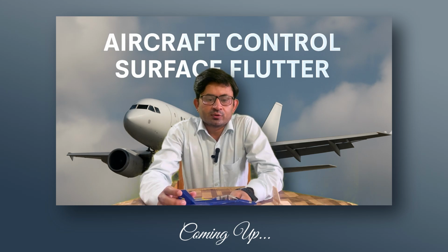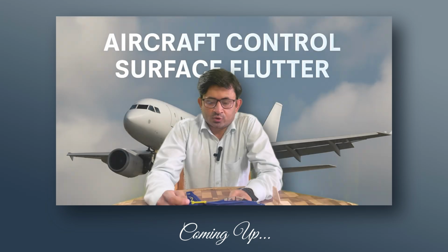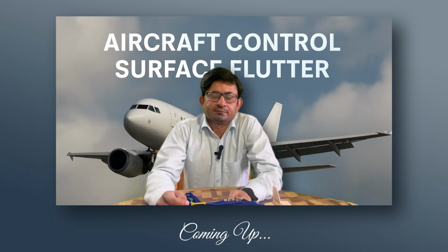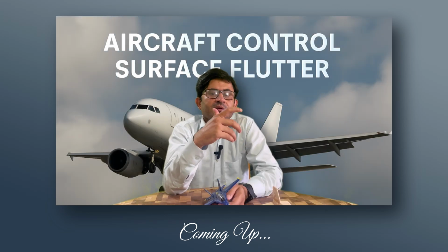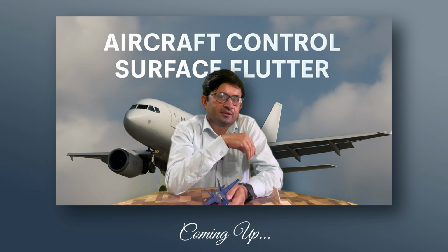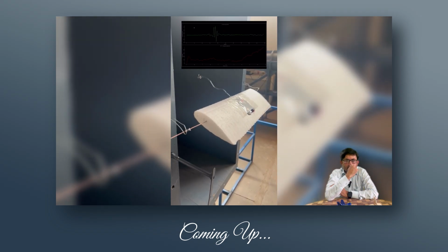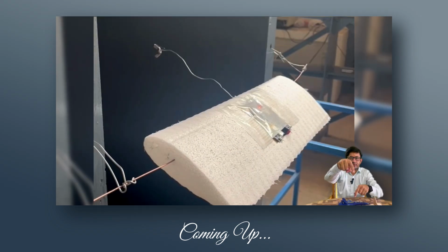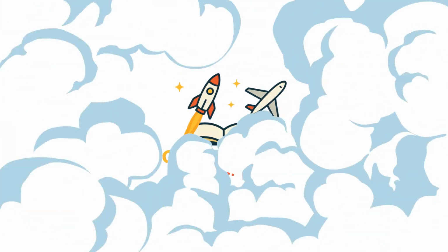I will be talking about one very important experiment that is called Flutter experiment. So the question is, first, what do you mean by Flutter? Flutter can occur when there is a coupling between aerodynamic, elasticity and inertia. Try to perform the experiment always. Some experiments you can perform cost effectively, like we did here. When we placed a small mass, the vibration suddenly reduced. Let's say this is a hinge line, this is an elevator, so we have to put some mass in order to move the CG towards the hinge line.